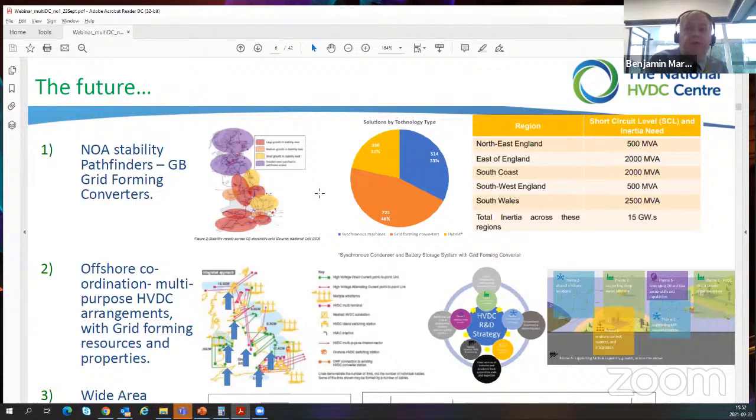We're not talking about fast response here, because the core issue, as was summarized, is the rate of change of frequency we're seeing. When you have a rate of change of frequency, that's the second derivative of your angle movement. Your converter is operating with a current loop control, which is trying to track the voltage angle on the system across any disturbance. Fundamentally, the challenge in a low inertia system is that the local angular movement is extremely quick and can become very chaotic based on the combination of the low inertia and the low short circuit level, bearing in mind that there's no such thing as an event which is purely frequency or purely voltage. Most are a combination of the two factors.